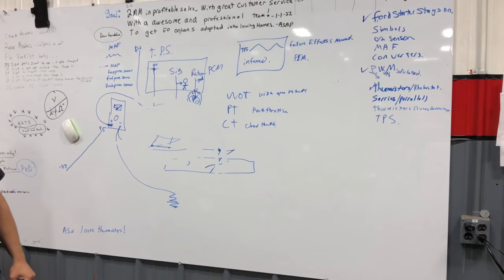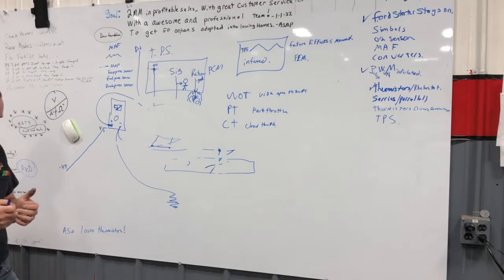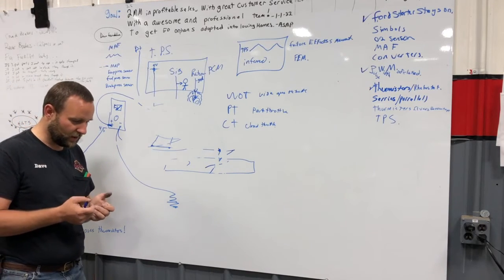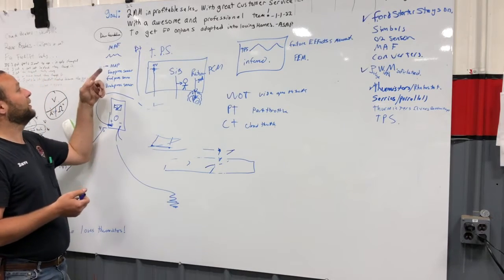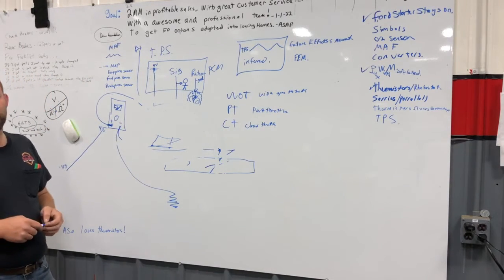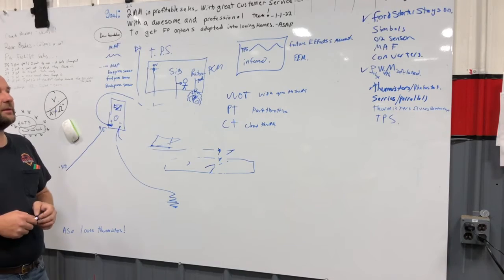Whatever you want to call him. But that's designed by the manufacturer. That's people programming it. Hey, what happens if we lose a TPS? Well, if we lose a TPS, we can get home if we just look at mass airflow and manifold pressure. Cool. That's cool.